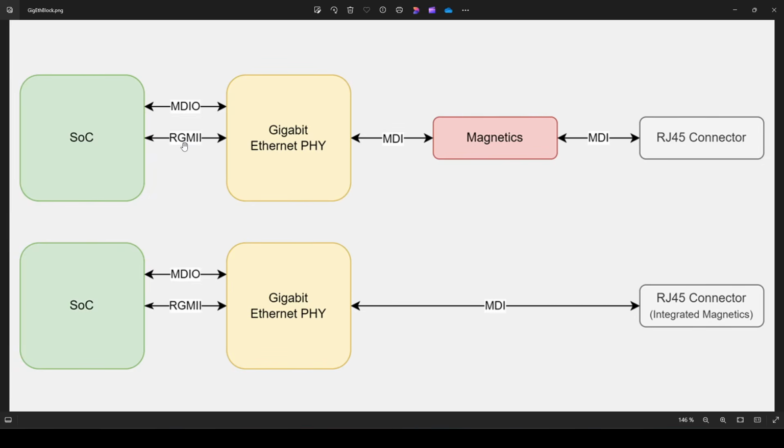The media independent interface for Gigabit Ethernet is 8 bits wide per receive line and one 8-bit wide bus for transmit, plus some other signals. Therefore, oftentimes we will find an RGMII, which is the reduced Gigabit media independent interface, which cuts that bus width down to 4 bits. This RGMII interface is mainly for data transfer.